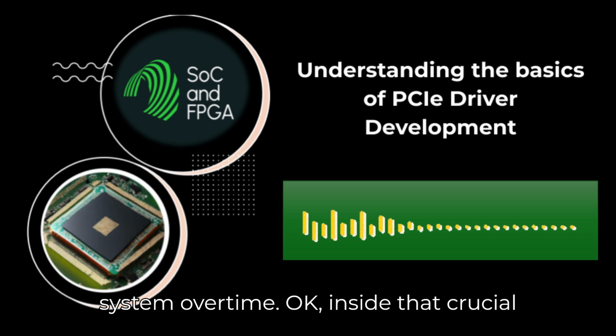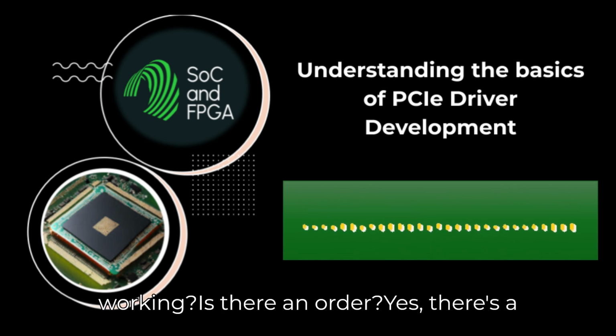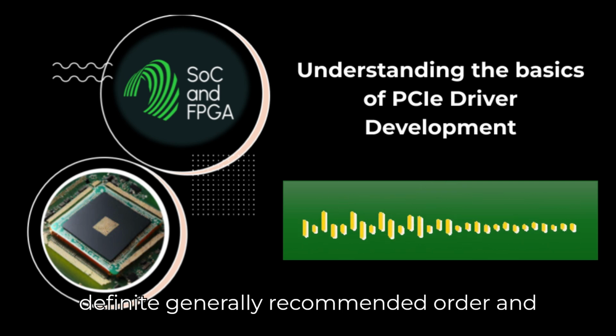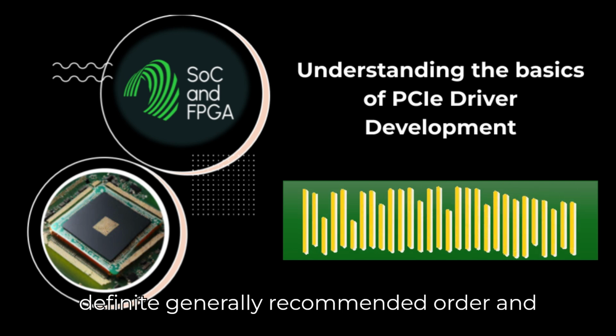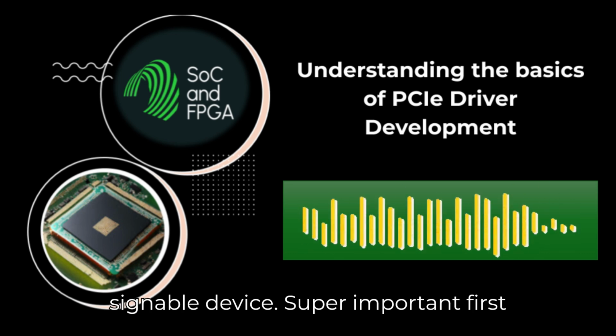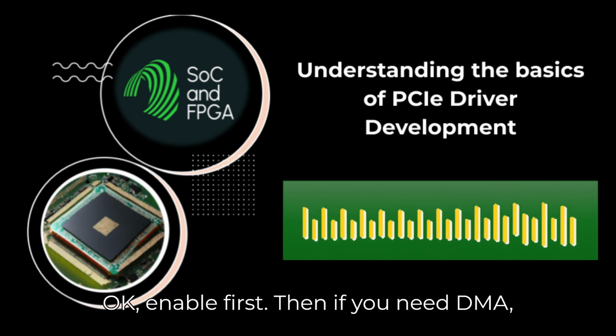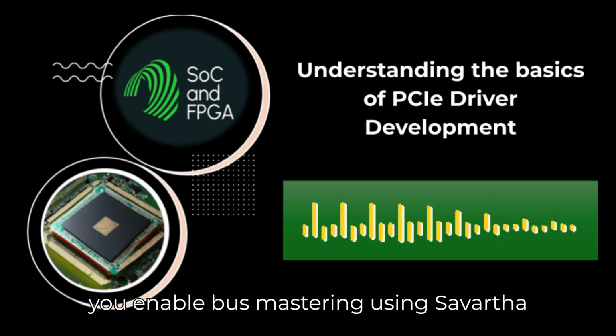Okay, inside that crucial probe function, what's the typical sequence of steps to get the device working? Is there an order? Yes, there's a definite, generally recommended order. And getting it wrong can cause problems. First, you enable the PCI device using pci_enable_device. Super important first step, and always check if it succeeded. Okay, enable first. Then, if you need DMA, you enable bus mastering using pci_set_master.